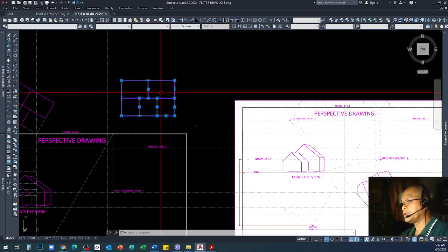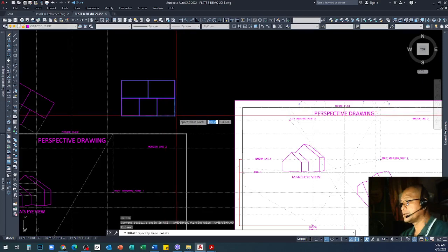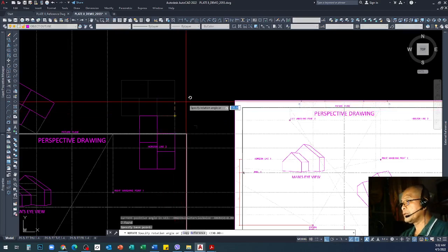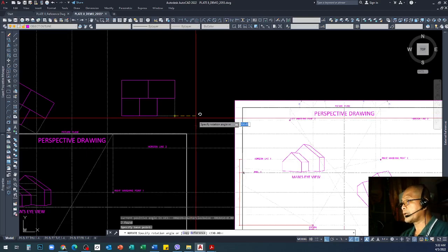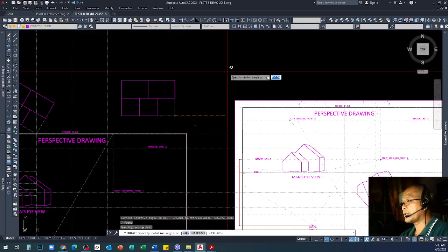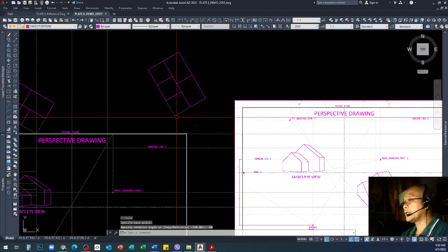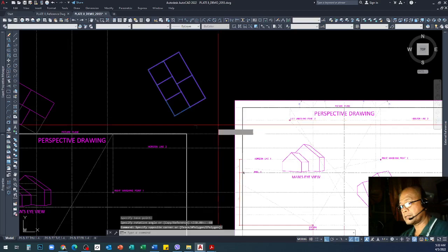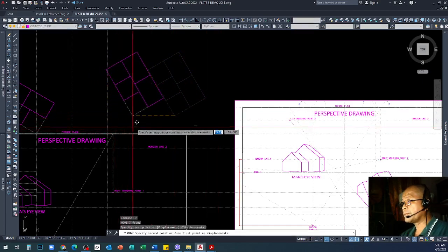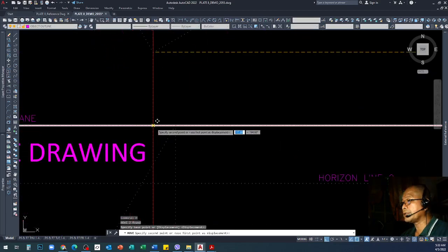So to do that, we need 30 here. So I need to rotate this top view counterclockwise. Again, as mentioned earlier, it is the angle that the CAD reads. So we need to do a rotate clockwise. So I will just enter 60, so that the angle on the right side is 30, and then you just move it and put it here.